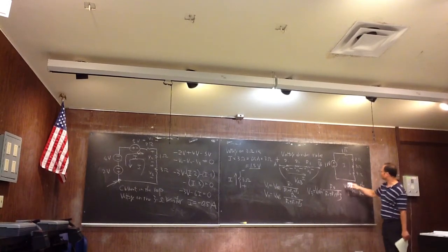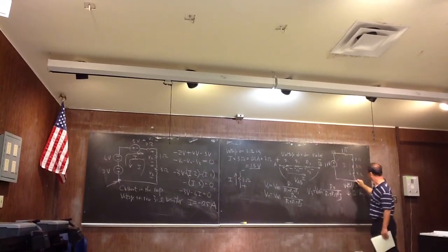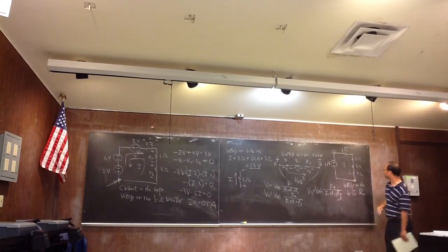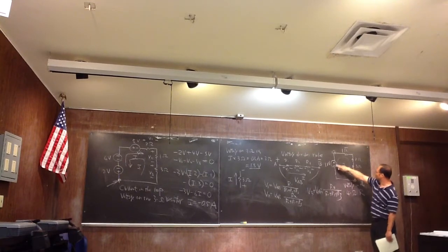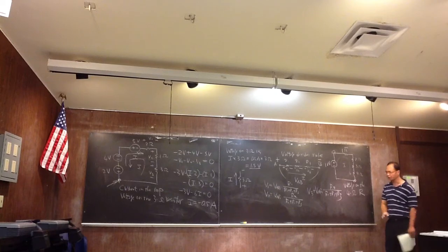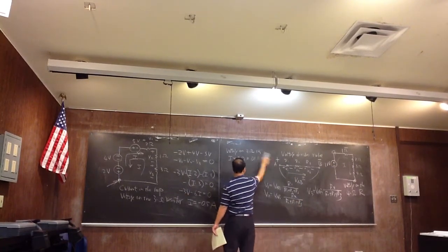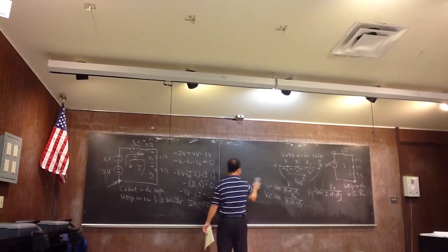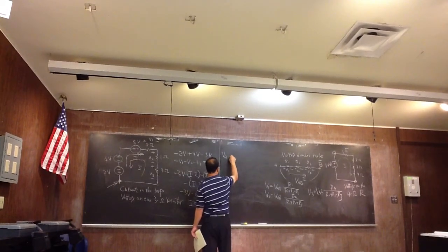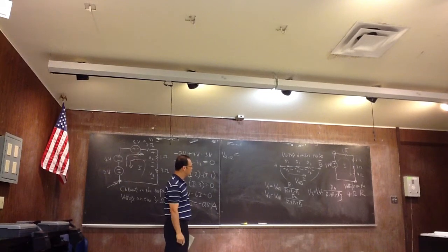Okay? So now you can see the voltage across these 2 terminals is 10 volts, correct? So between the 10 volts you have these 4 resistors in series. If I use the formula here, with just one equation I can get the answer. So the voltage on the 4 ohm is equal to what, if we just look at the formula?